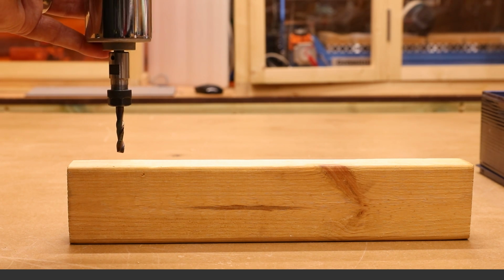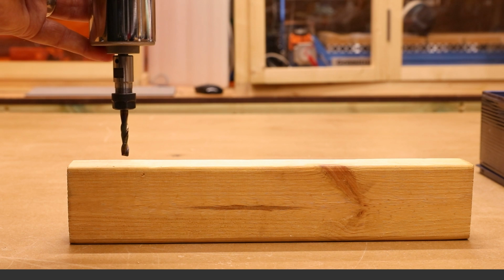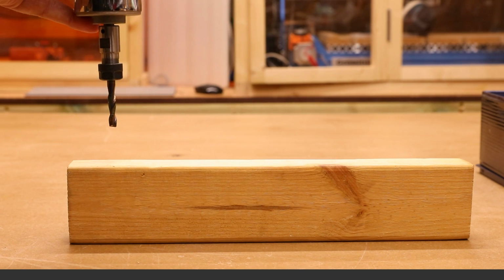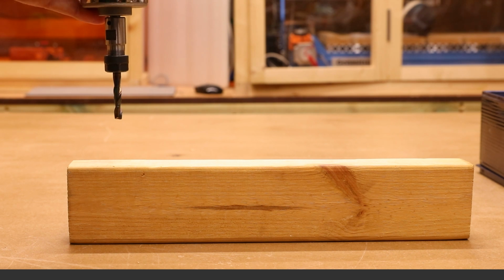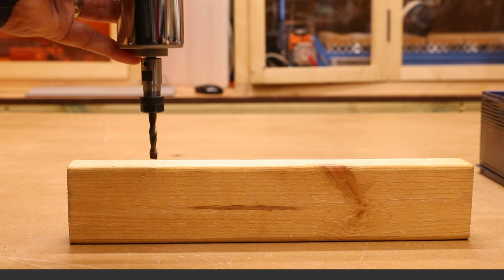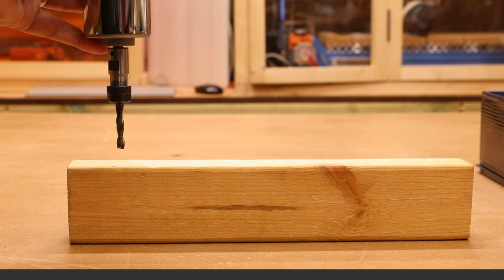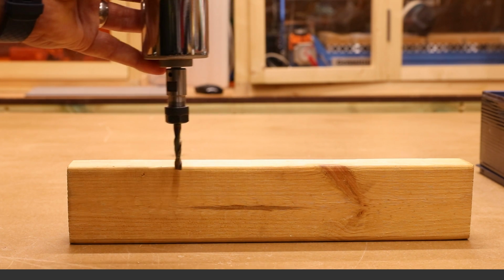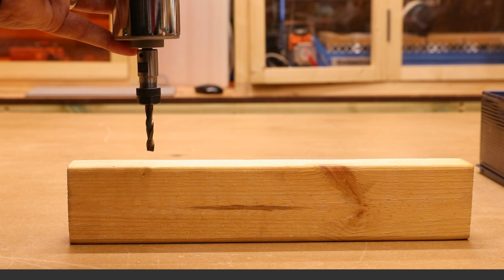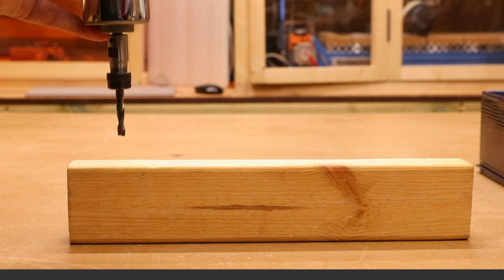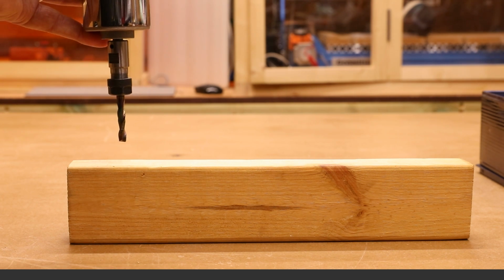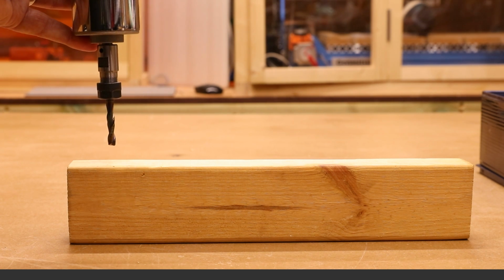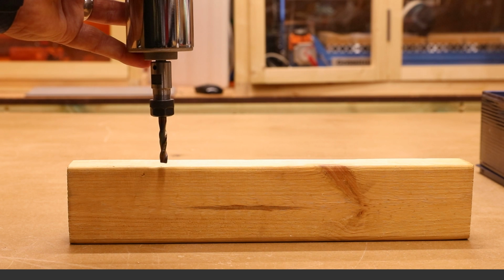It can be done over a distance, so perhaps 100mm, and it will slowly come down over that distance till it goes into the material. It can be done at a certain angle. For example, you can define it at something like a 45-degree angle to come in as you like. It can be done over one consistent pass, or it can be done either by zigzagging its way down into the material or even spiraling, which is a similar thing. You can mix both of these. For example, you can say you may want it to come in at a 45-degree angle over a 20mm distance, and that is what it will calculate into it.